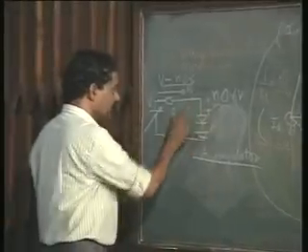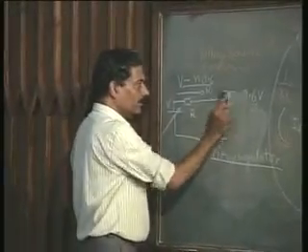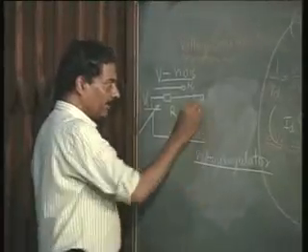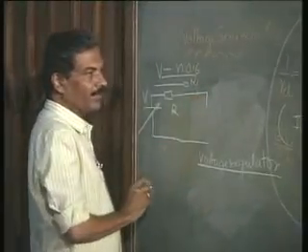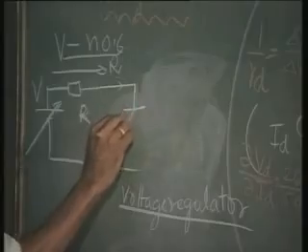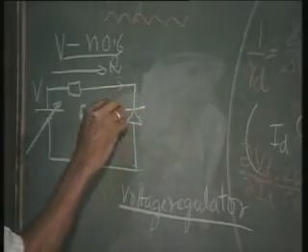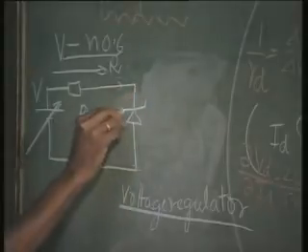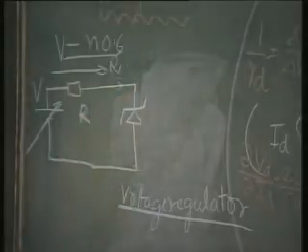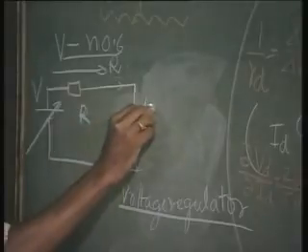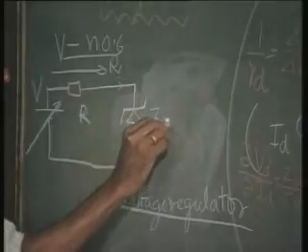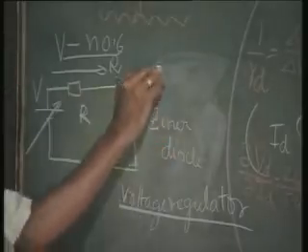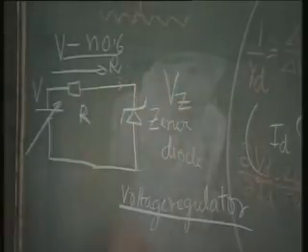So, the entire region can be used; instead of using a string of diodes, we can use a Zener diode. The symbol for the Zener diode is the same diode used in the reverse bias mode, but in the breakdown region. So, you have this breakdown region indicated by this symbol. This is the Zener diode, and the Zener breakdown voltage is Vz.